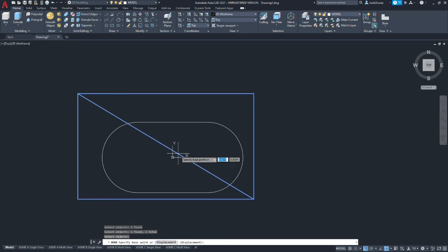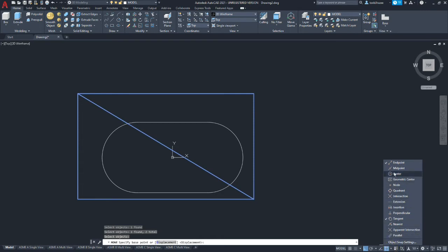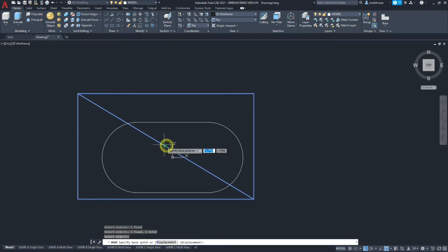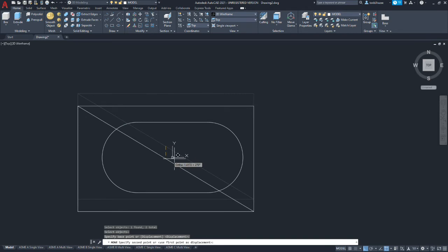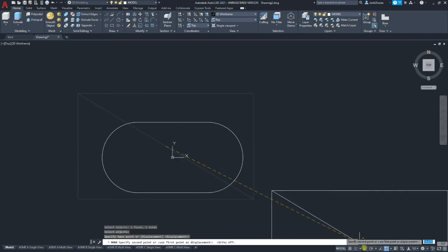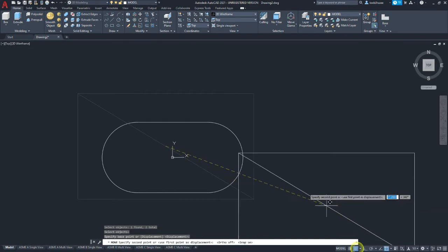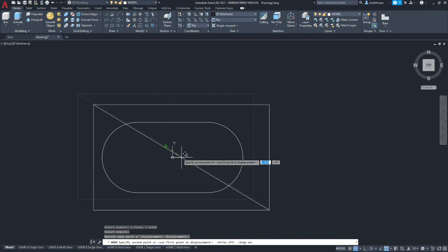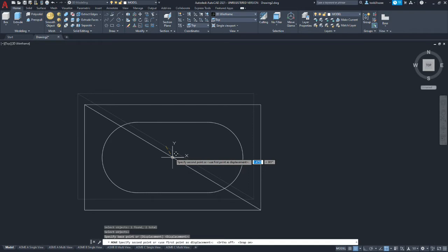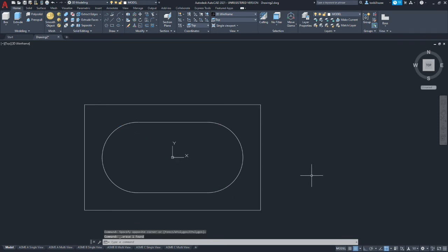And we're going to move from the object snap of midpoint, and then we're going to turn ortho off, and we're going to turn the grid snap on so that we can hit the origin. Okay, let's delete our line that was making center. Yeah, I don't know, proportions, that looks pretty good.